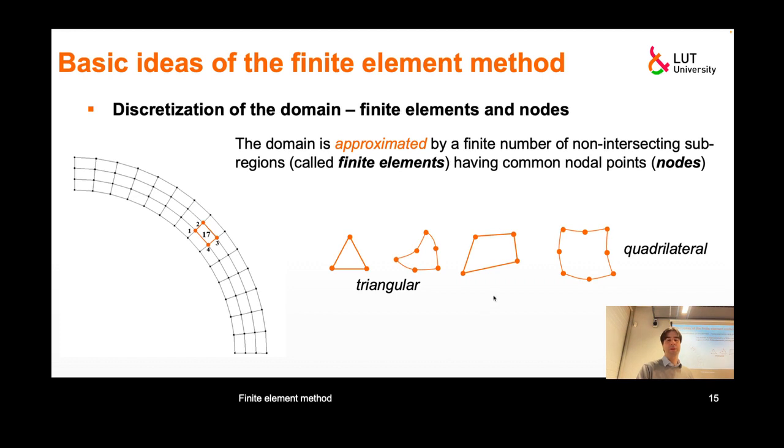Or they might be a little bit more irregular in form, still quadrilateral, but it's not necessary that they are of this shape as in my picture. Not necessarily rectangular ones, I mean. But they may also have nonlinear boundaries. We are not limited to elements with linear boundaries, of course. They might be boundaries described with second-order equations, which is actually pretty often used.